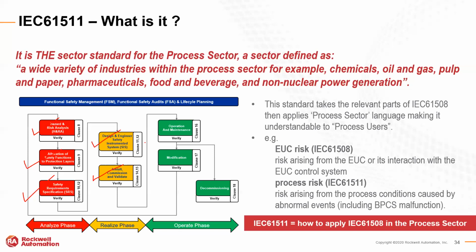So you want to follow the safety life cycle and make sure that any changes that are made, you go back now. So notice this line. You want to go back here all the way to the hazard and risk assessment and say, okay, the hazard and risk assessment assumed that information A, B, and C were correct. Well, maybe you just changed B, okay? And so now B is no longer an adequate assumption. So now you have to go back into this loop and change that because it's now an inaccurate assumption and is not valid. So that is definitely where we want to go through and do that, okay?